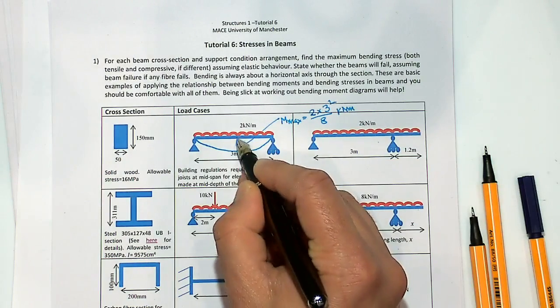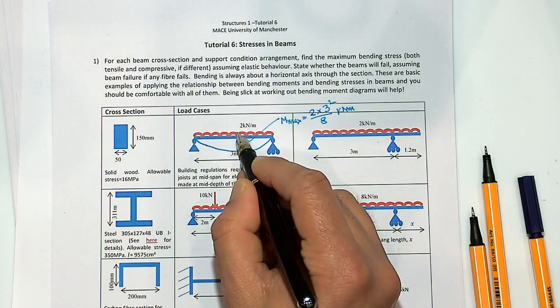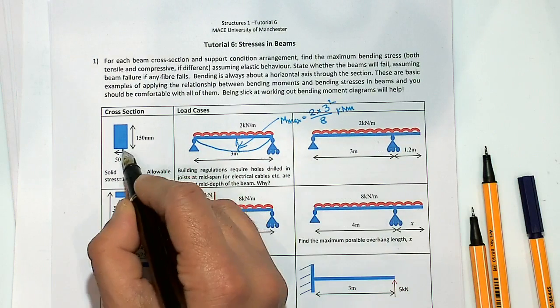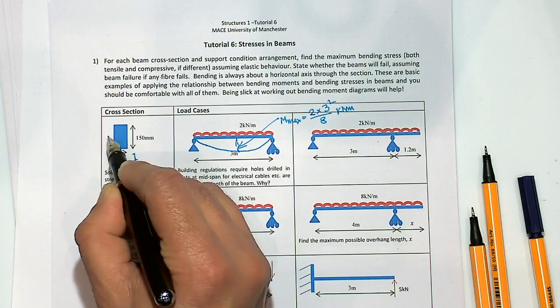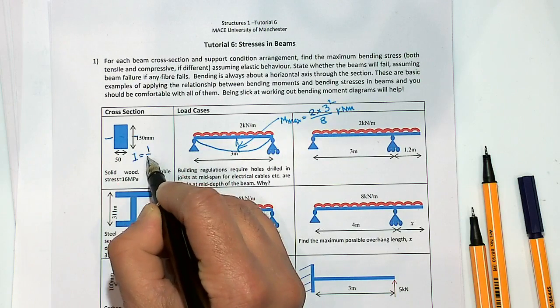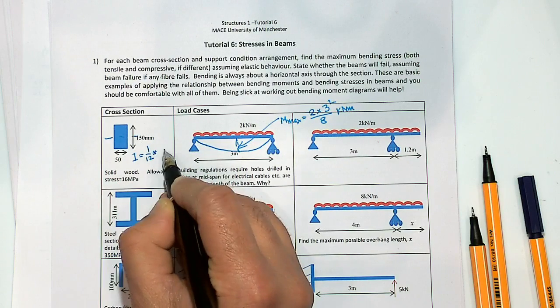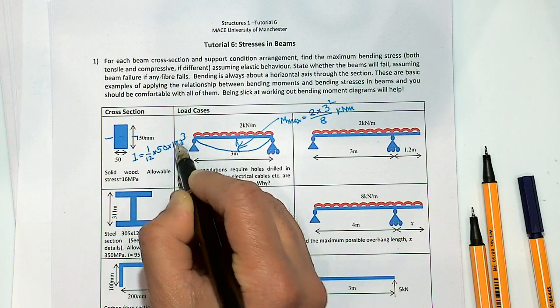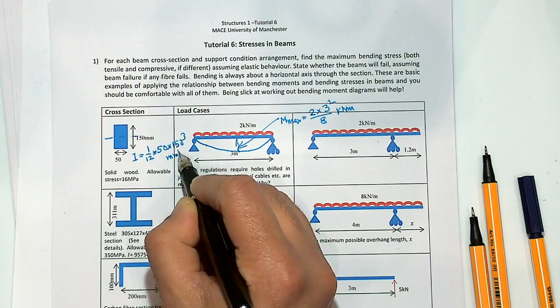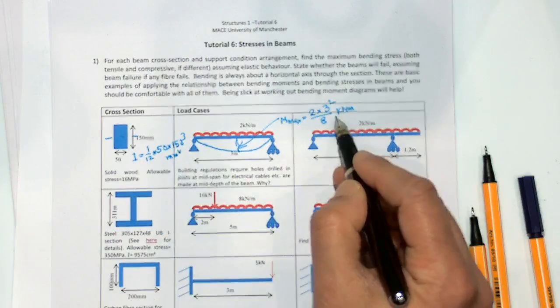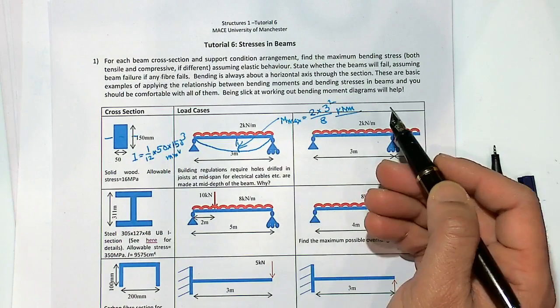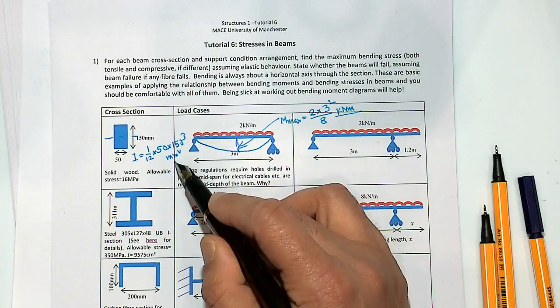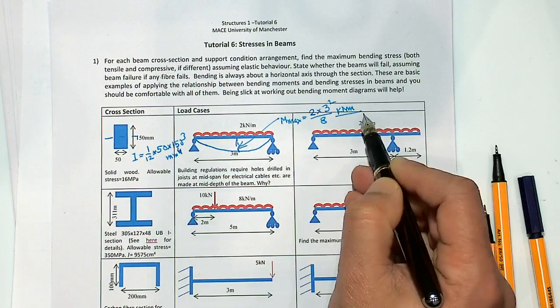So you will have a maximum stress at that location. You know I, about this axis, is 1/12 times B, which is 50, times 150 cubed, that much millimeter to the power 4. So convert kilonewton meter to Newton millimeter, for example, or millimeter to the power 4 to meter to the power 4.